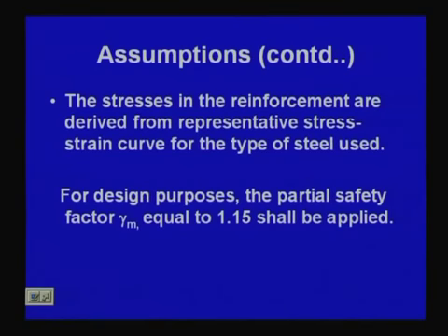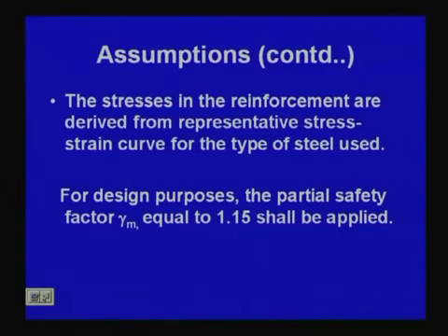For design purposes, the partial safety factor gamma m for steel we consider 1.15. So, if fy is the yield stress, we have to consider fy by 1.15, for design purposes.